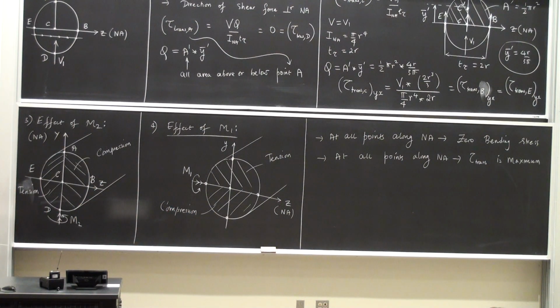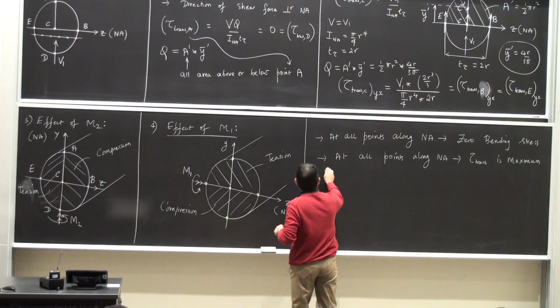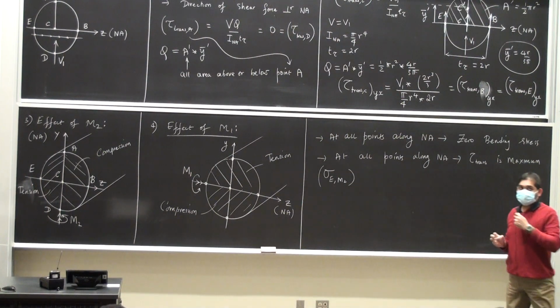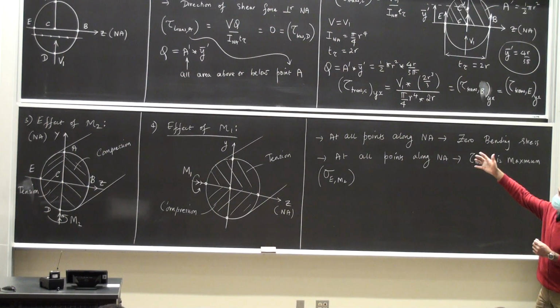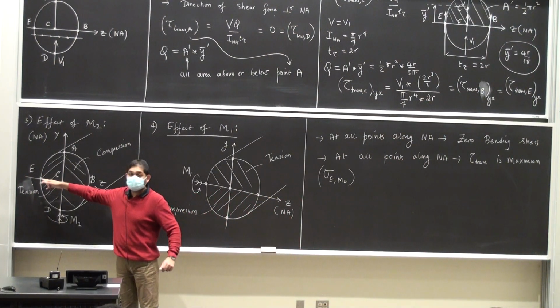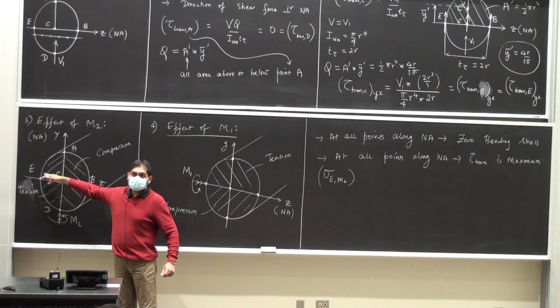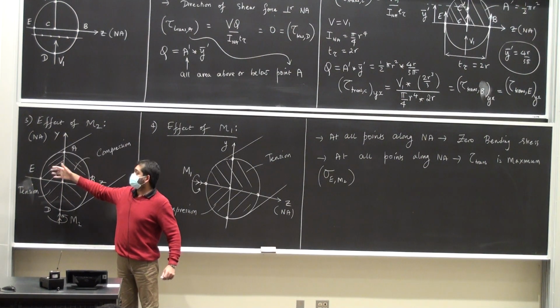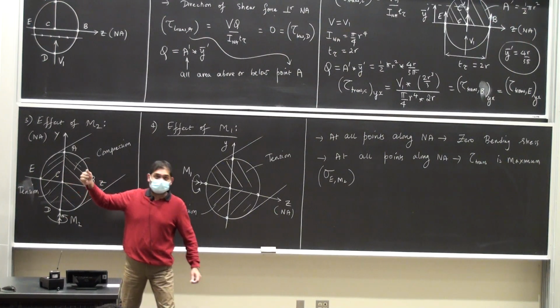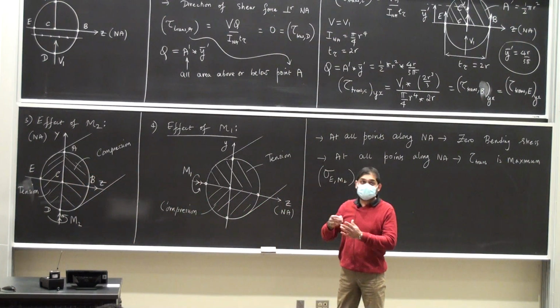And so it is now easy to calculate. If I look at the bending moment M2, all of these points are zero, so the bending stress at E and B due to M2 is zero. Okay, so sigma at E due to M2, I can outright find out that this direction is going to be along which axis? The direction of the bending stress at the point E, so which directions are the fibers getting pulled or pushed? They are getting pulled or pushed along the x-axis. Right? Which means that the subscript is going to be the same here, the normal is also the x-axis.